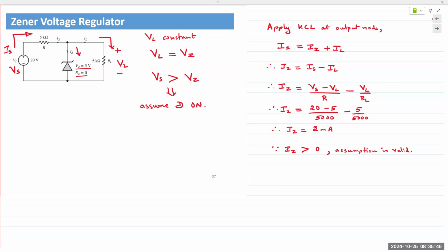Okay. So as I was saying, the key thing to keep in mind is voltage output. Output voltage is always taken in parallel across the Zener diode. And if there's an increase in voltage, which means an increase in source current, the Zener allows a pathway for the extra current to flow through, thus keeping the output voltage and the output current constant.